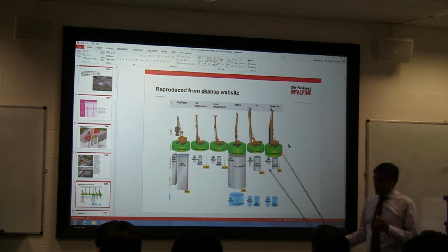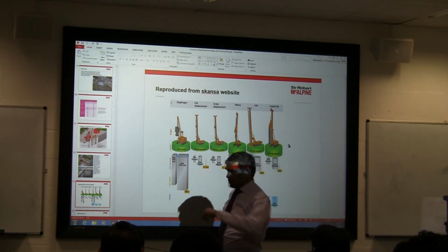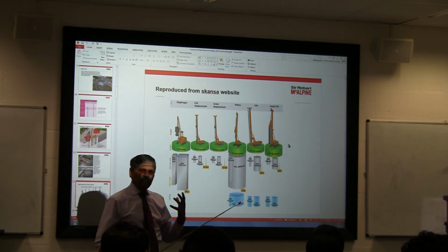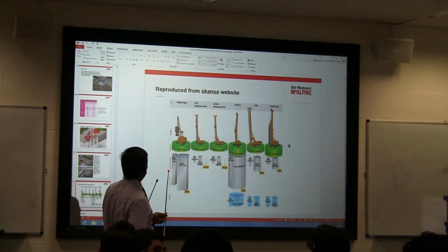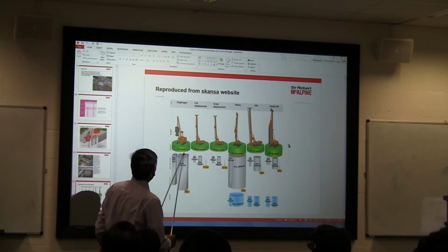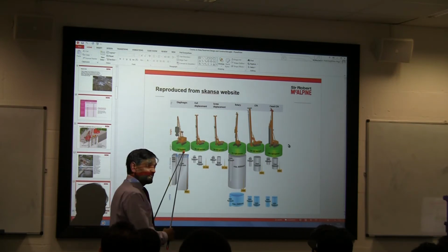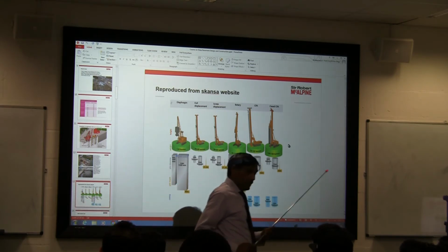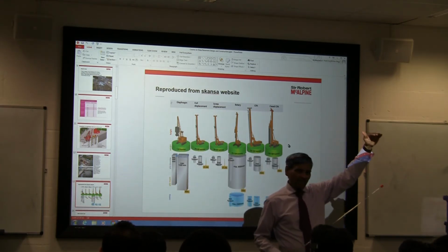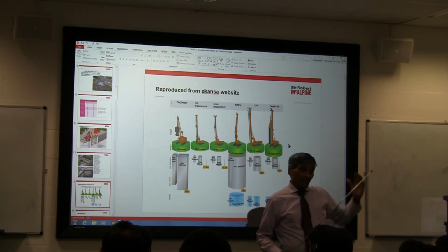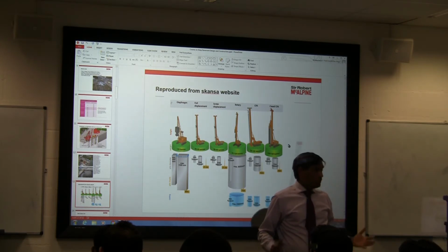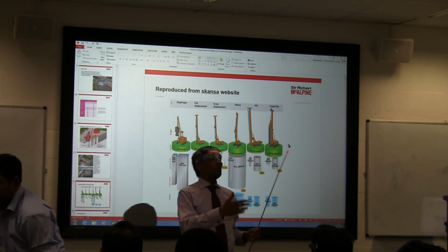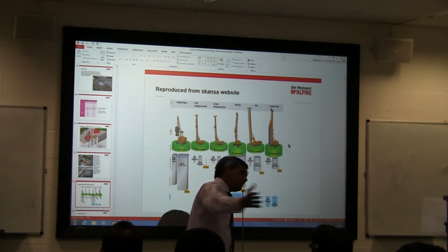Right. This gives a summary of what diameters we can do, and what sort of weights we have to think about. Because if you talk about a diaphragm wall, we're talking about that kit being 120 tons. So it's a massive kit. It's standing there. Remember, we are working from the ground level, where the ground may not be good enough. So you may have to improve the ground, even in temporary condition, to take that load. So what we call piling mats.